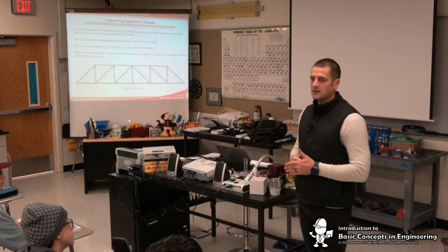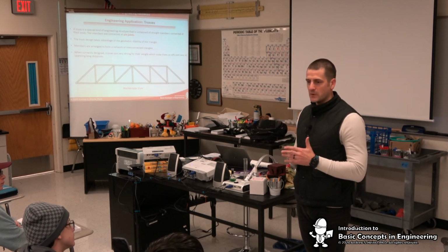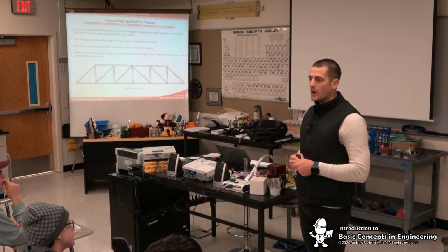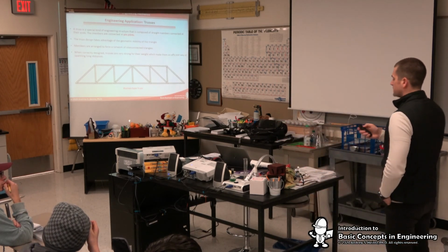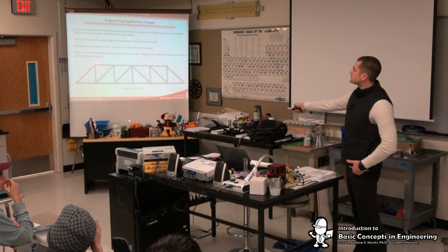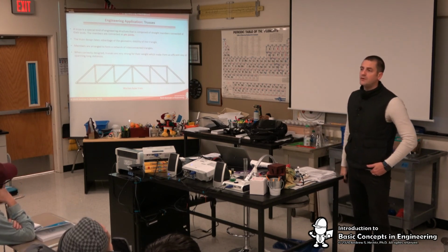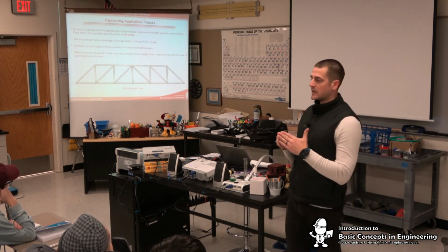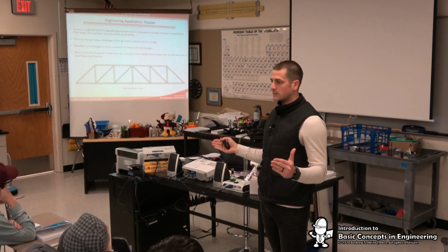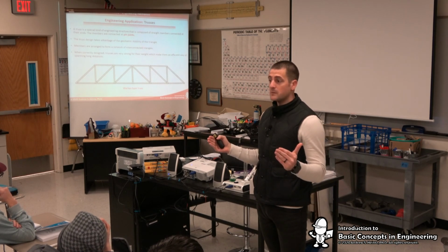Now functionally, we're not going to build a bridge with a freely rotating joint, right? We weld it, we rivet it together, right? We all get that. But from a design standpoint, each one of these members we think of as able to move on its own. It can rotate around those points. And again, the idea is as long as we build our structure correctly, it will be stable enough that it won't be able to rotate.